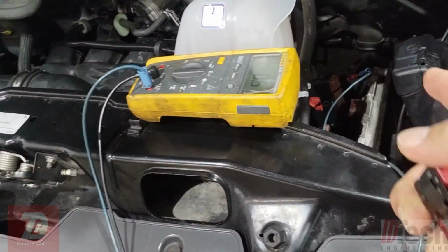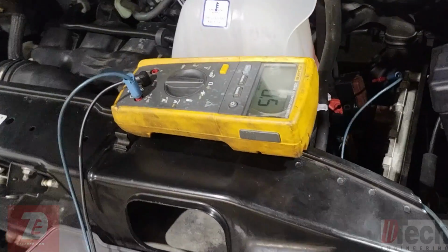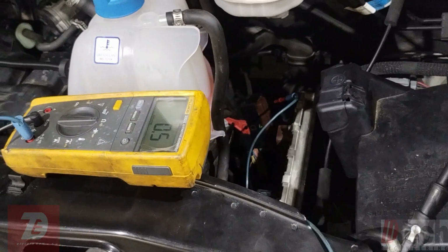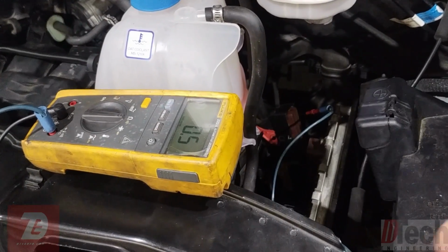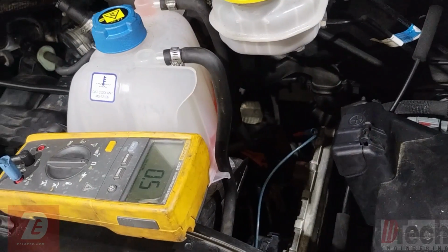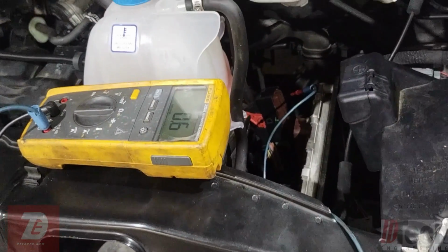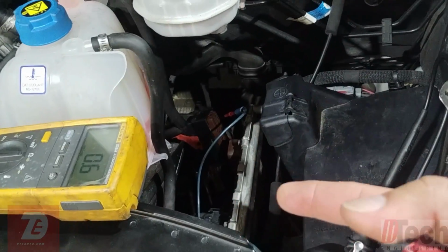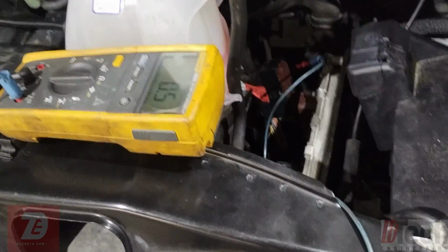Our first test, when we checked the circuit to ground, thinking we were going through the solenoid to ground, was sort of right, but obviously incorrect, because in a known good situation, yes, we would have gone to ground. But we obviously have a direct short to ground, so it's going to give us the same result.